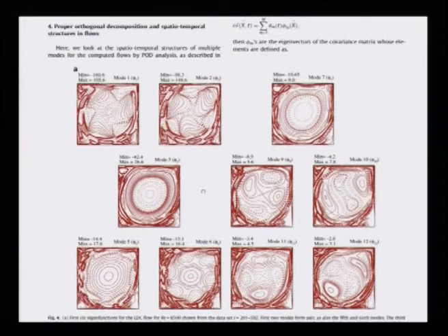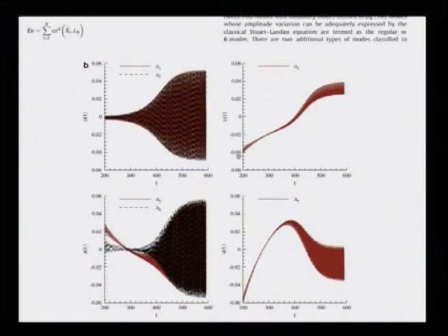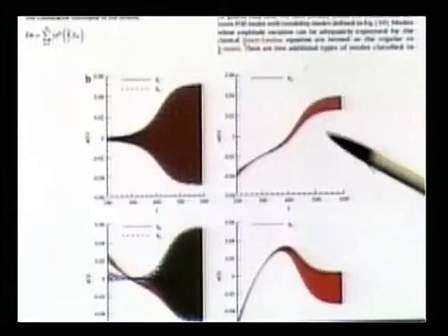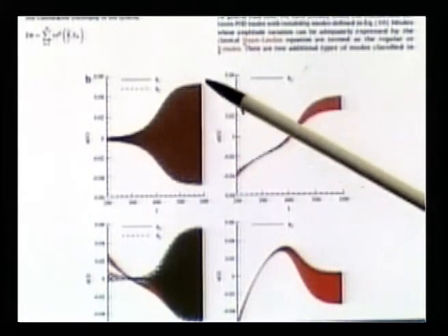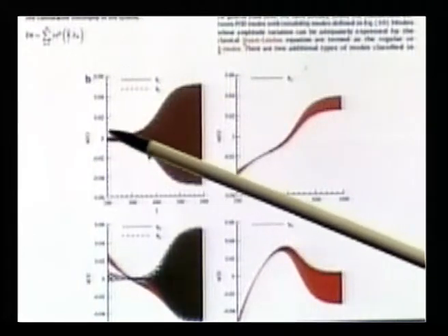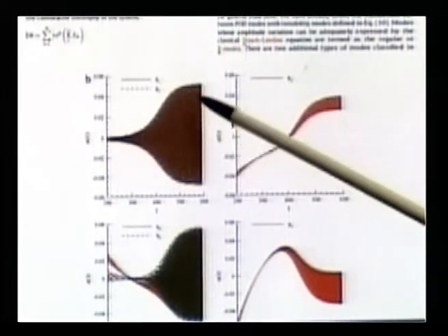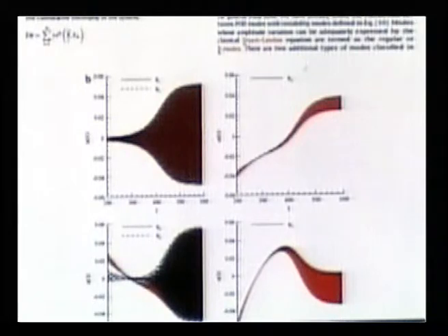And how do we know? Well, you have to plot the amplitude functions. You will have to plot a_m(t), and once you do that, well, here are the pictures. A1 and A2, as you can see, are plotted here. They do indeed follow the Landau equation. That is why we call it a regular mode. This is your mean 0 line, and you are seeing the fluctuations, right.